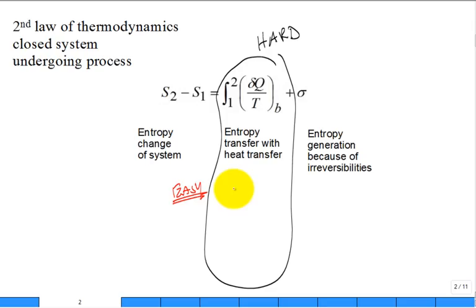If del Q is always equal to 0. What does that mean? It's adiabatic. Don't forget the obvious, right? If it's 0, it's 0. It's pretty easy to calculate then. It's nothing. Then the other case, so this was adiabatic. The other case of when it's really easy to calculate is temperature's constant. It's T is equal to a constant. Not T is 0, but temperature is constant. That's called isothermal, because then that T can come outside the integral.